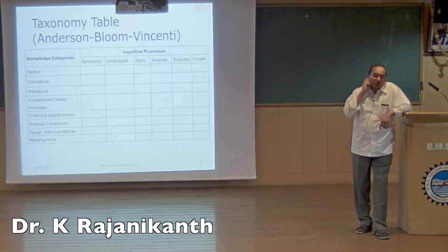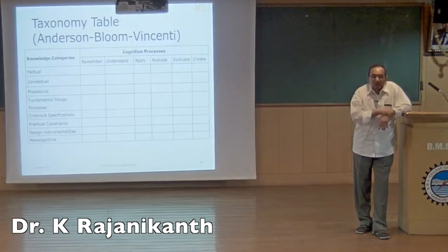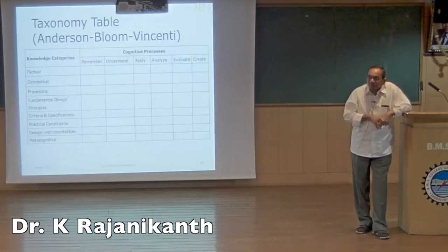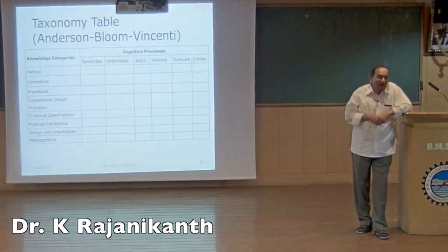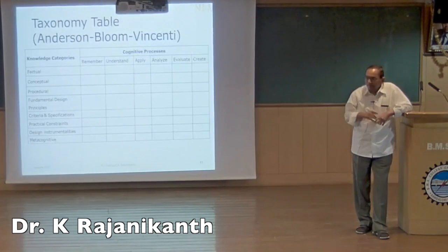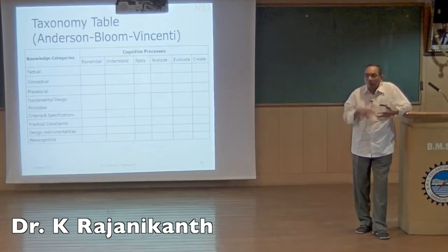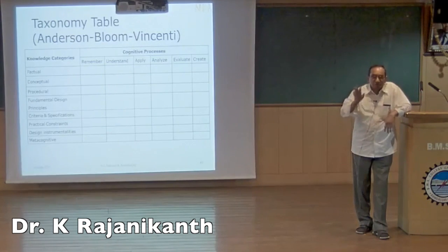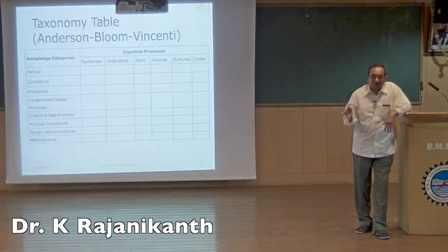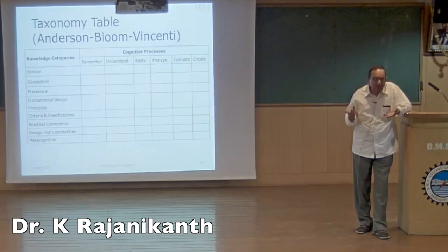Which also means that we should be conscious. Like for example, almost all of us do teach digital electronics. We teach them 74LS00, 74ALS00. Right? Our electronics faculty, they would know. But not even one student, and many times even faculty really do not know what is meant by ALS, what is meant by LS, why those terms are used like this, what does it mean to say it is 7400, on the other hand 74LS00, 74ALS00, what do they mean? What do they mean in terms of the specifications?